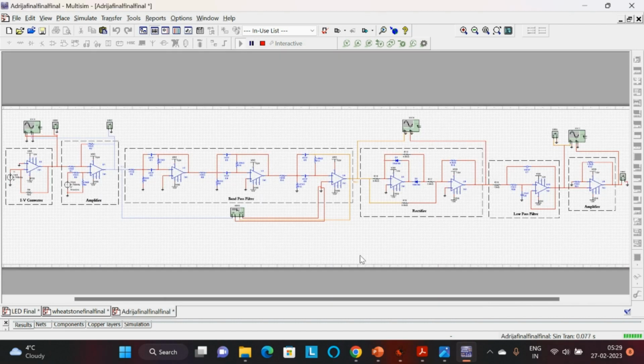This is the receiver part of the distance sensor circuit. The photodiode detects the 3.765 kHz frequency from the LED along with other surrounding noise light frequencies. To remove this unwanted noise, the output is passed through a bandpass filter, which is then passed through a rectifier and a low pass filter to give a DC output.